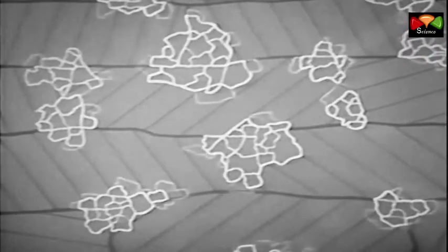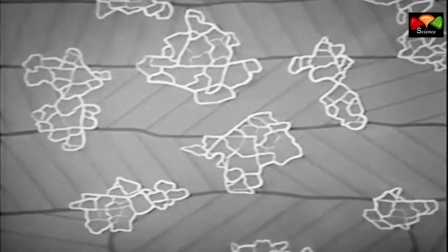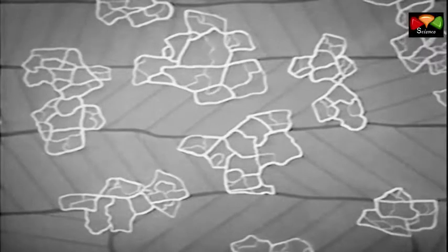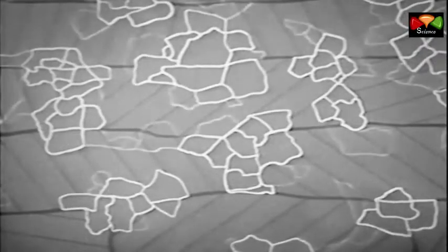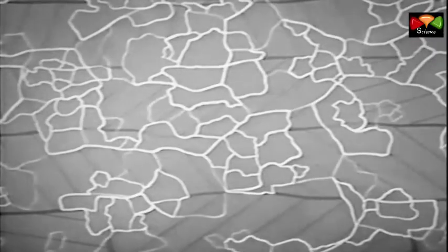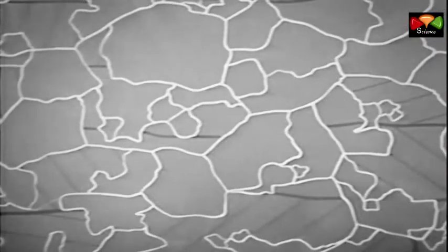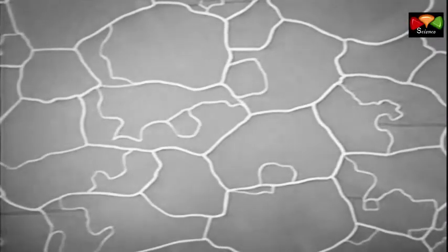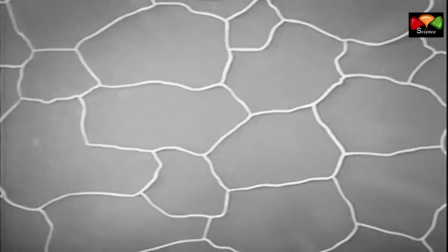As the metal is heated above the recrystallization temperature, but below the melting point, these stress-free crystal nuclei grow into new equiaxed grains by merging with the other nuclei and by accretion of material from the surrounding stressed metal. At elevated temperatures, the new grains may become quite large. The alloy is now in its annealed or soft condition.